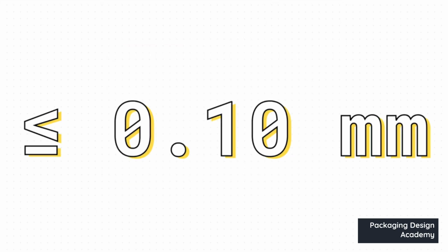And you know, it's not just about color. We also have to talk about registration. That's how perfectly the different color plates line up with each other. And for modern printing, the target is an unbelievable 0.10 millimeters. That's about the thickness of a single human hair. Why does this matter so much? Well, bad registration is what makes small text look fuzzy or makes QR codes impossible to scan. This is a critical spec.